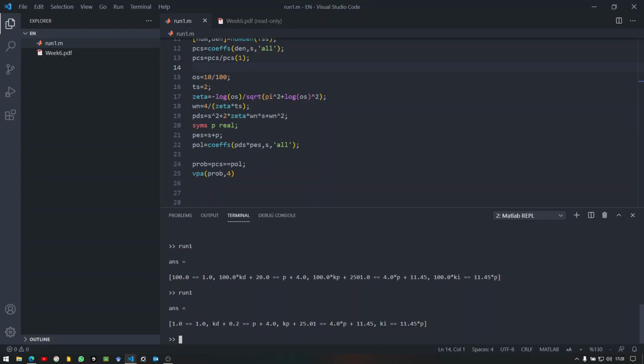Now, at this point I can see that Kp, Ki, and Kd, 3 parameters of the controller, and P in addition makes 4 unknowns, but I have 3 equations, since this is trivial here. This means that I have a free parameter and I have infinite amount of solutions to choose from. Now here it seems like it could be a good idea to use P as the free parameter and determine what Kp, Kd, and Ki will look like.